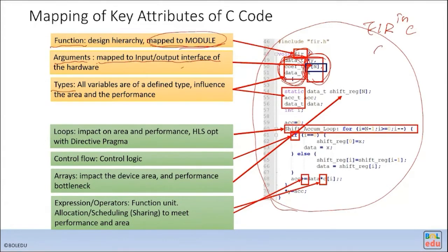Why do we want to use C, C++ for high-level synthesis instead of Python? One of the reasons is C, C++ is strongly typed. For every variable, you have to explicitly specify its data type. And with the explicit data type, you know the resource at compile time. But Python or Java, those high-level languages are so high level that they don't have a specific data type until runtime.